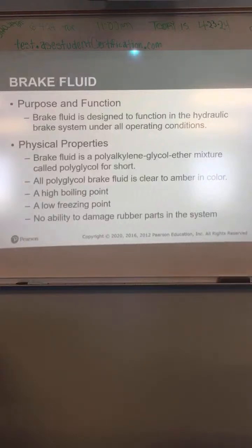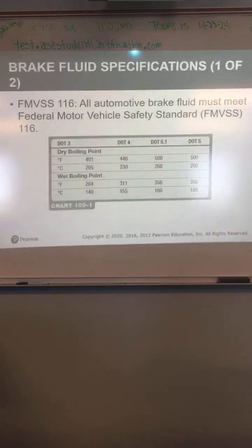All right, brake fluid, it's designed to function in the hydraulic brake system under all operating conditions. It should not be able to evaporate or freeze. We talked about that yesterday. It has to have physical properties. Polyalkylene glycol, either mixture or called polyglycol for short. Brake fluid is typically clear to amber in color. It will have a high boiling point and a low freezing point. No ability to damage rubber parts in the system. You do have rubber parts in the system, okay, in your brake calipers, in your master cylinder, sealing cup, stuff like that. It has to be able to be friendly to the rubber components.